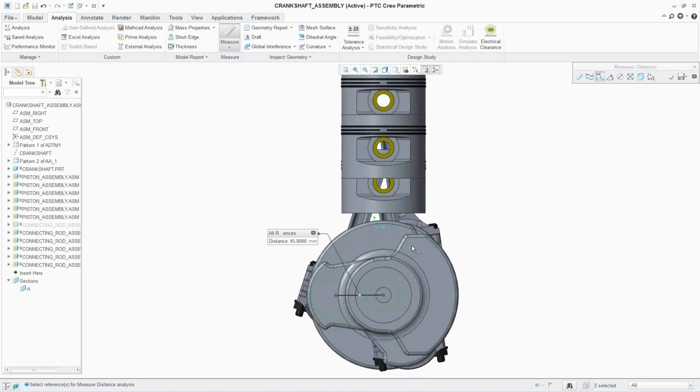So this is the crankshaft. It's going to rotate around. And when this point here, the point where the connecting rod connects the piston to the crankshaft, when it gets to the top, that piston is going to be at its peak height. And when it rotates back around to the bottom, that piston will be at its bottom height, what I showed in the diagram in the Mathcad worksheet. So this distance here is half of the total distance the piston will move up and down.